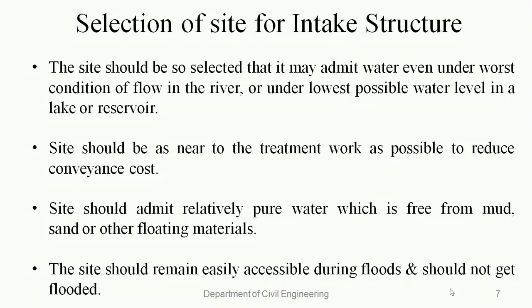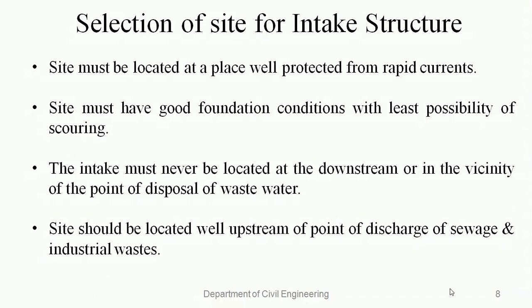The intake site should remain easily accessible during floods, and it should not get flooded, because if it does, then the entire pumping assembly and other important parts will get heavily damaged. The site must be located at a place well protected from rapid currents. The site must have good foundation conditions with least possibility of scouring.